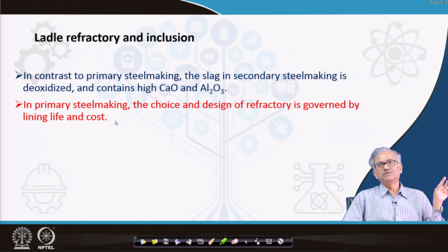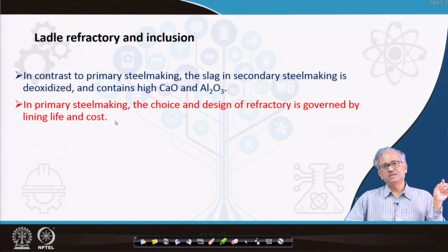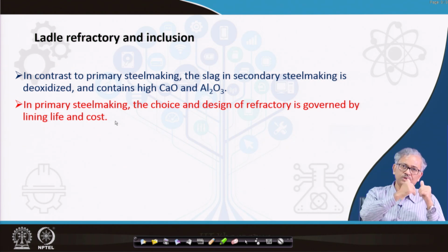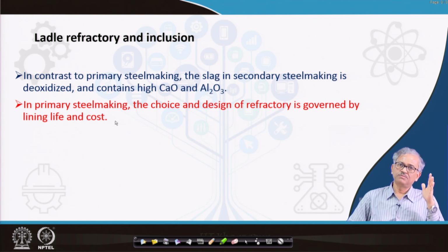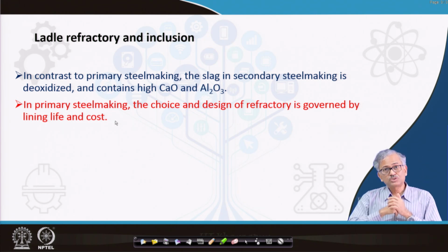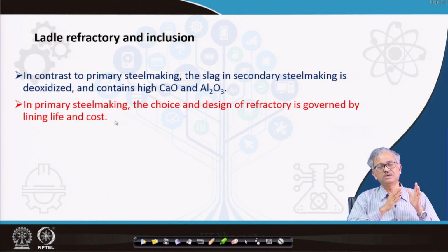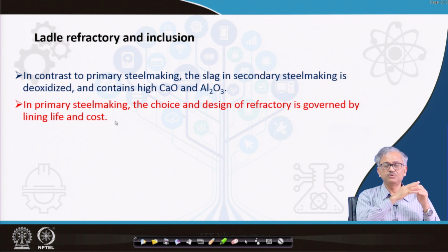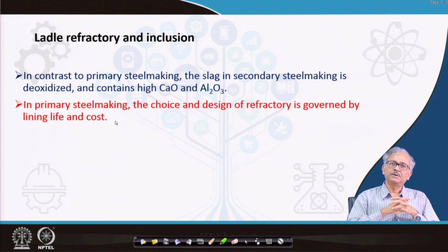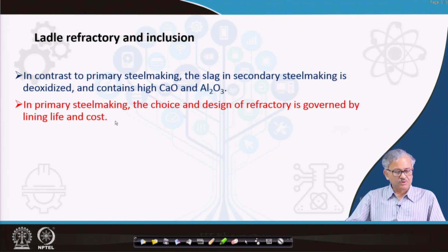To reduce the mechanical erosion, which is because of shear stress between the liquid and the refractories, the refractory has to have very good wear resistance such that it does not wear off very much, and the thermal shock resistance also has to be very high. If the shock resistance is not good, then they can crack and the liquid can penetrate, and then mechanical and chemical erosion will be more. So those properties are very important. I will talk about that.